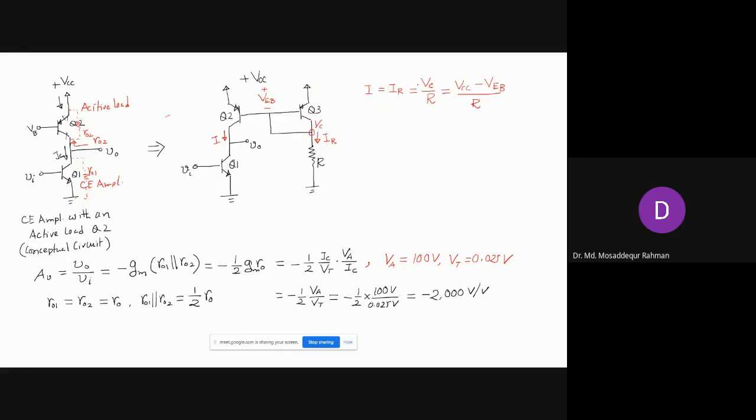So that's called the reference current. So by adjusting the resistance R, you can fix this reference current, and that same current will be reproduced here.